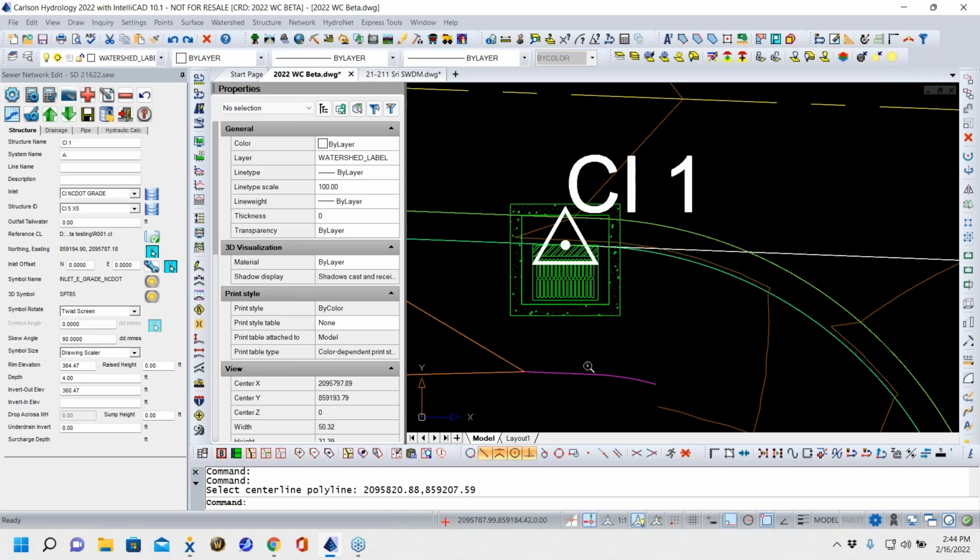I put this one catch basin in there with 0,0, comma 0 at the insertion point, the back of curb for me, because that is the rim elevation I'm looking for and what will be staked in the field where I'm at. Now, check this out. So hopefully this explains it. Now, in my CAD file, Ron, this is drawn 1-to-1. So if it's 5x5, it should be 5x5 on the dimensions. But right now, it's being scaled.